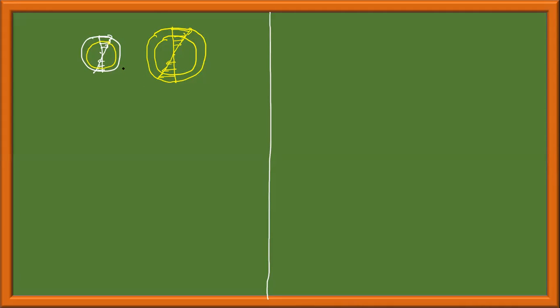That is how we have to understand this region. What is there in this region? We don't require material because this is subject to very minimum stresses. Maximum stress is at the outer fiber here. Then why is the material required here? Let us remove that material. Then we require the material only in this thickness. That is why propeller shafts are generally hollow. I have seen the propeller shaft of trucks. It is hollow, not solid.